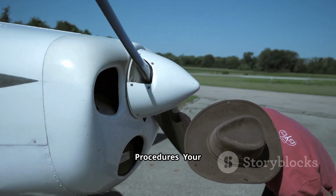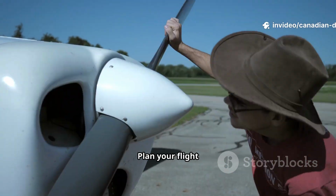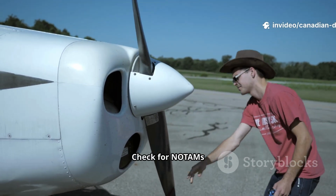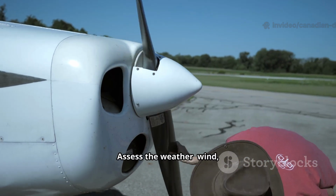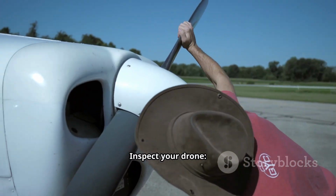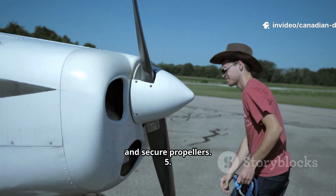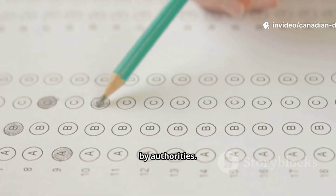5. Pre-flight procedures, your legal duty. Before each flight you must: 1. Plan your flight using the NAV Canada tool. 2. Check for NOTAMs, notices to airmen for temporary flight restrictions. 3. Assess the weather: wind, visibility, precipitation. 4. Inspect your drone. Check for physical damage, battery levels, and secure propellers. 5. Ensure your registration and certificate are available if needed by authorities.